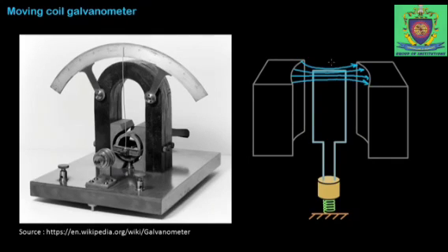So now, from the magnet it gives a radial magnetic field. So we understood that there is a magnet over here and there is a coil at the center, and we know some wire, let us connect to that. Okay, so for that coil let us connect the wire. When the current carrying coil is placed in a uniform magnetic field, it experiences a torque, then it starts to rotate like this, correct? It starts to rotate like this.